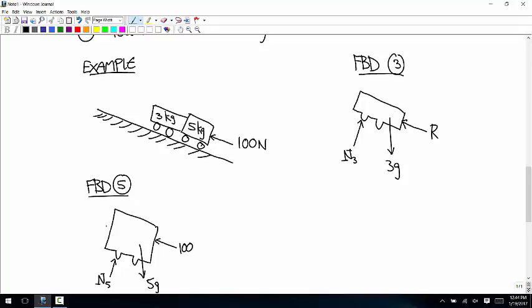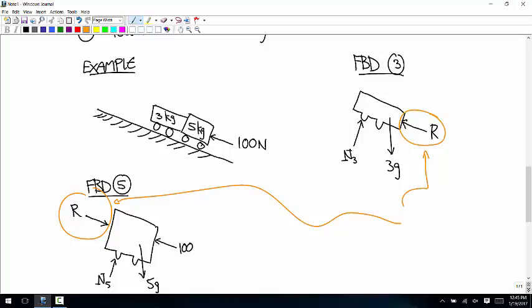And then over here, we have the force that comes from the same contact as this. And so Newton's third law says we're going to keep that same variable name and just flip the direction of the force. So this. And that's also a pushing contact, so it ends up being perpendicular to the surface of contact toward the chosen body. So this and this have to satisfy Newton's third law.